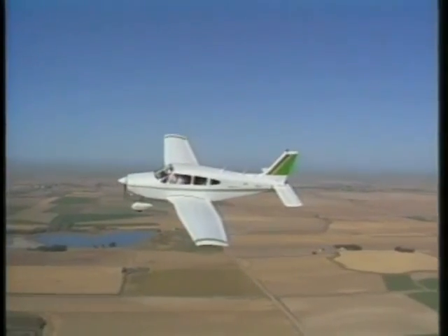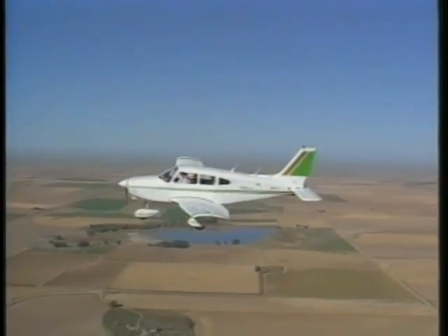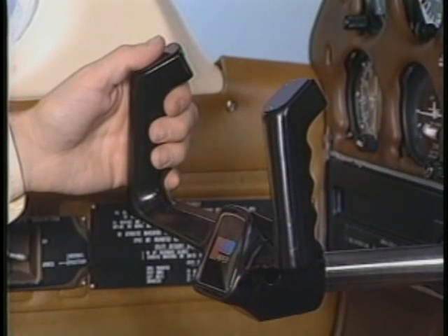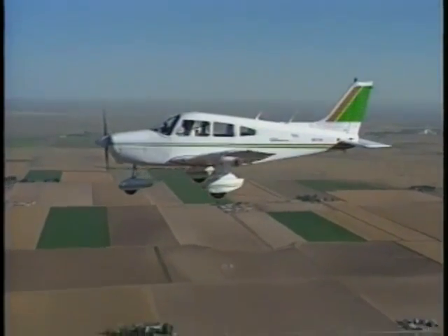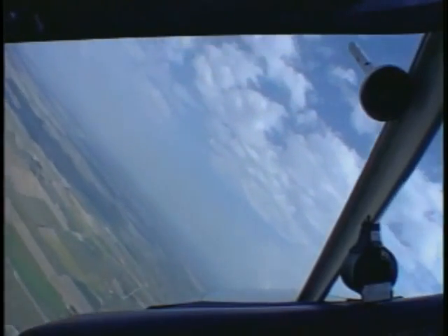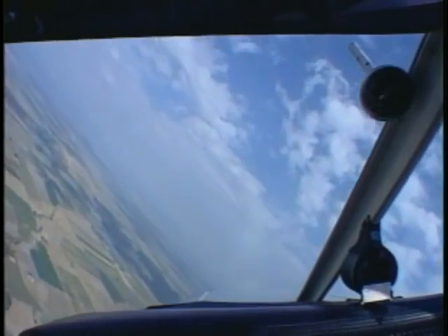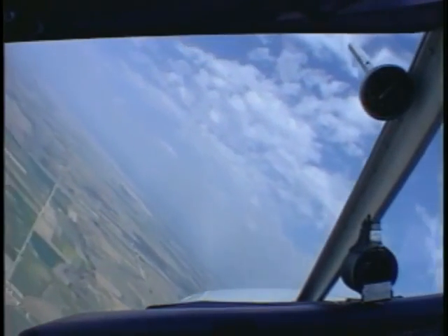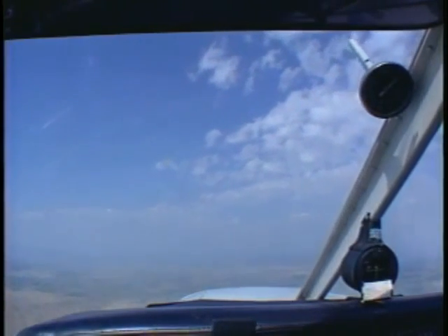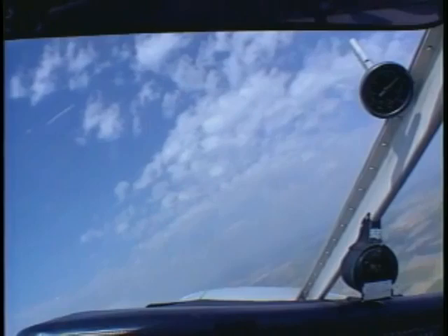If you use stabilator trim at the start of the turn to relieve control pressure, be prepared to exert forward pressure on the control wheel as you recover to prevent the airplane from climbing. Then retrim as necessary. While practicing the maneuver, a steep turn in one direction might be followed by one in the opposite direction. As you begin your rollout on the predetermined heading, gradually reduce back pressure until the airplane is wings level. Then begin to increase back pressure as you immediately roll into a 50-degree bank in the opposite direction.